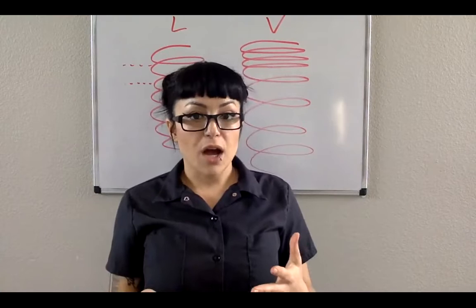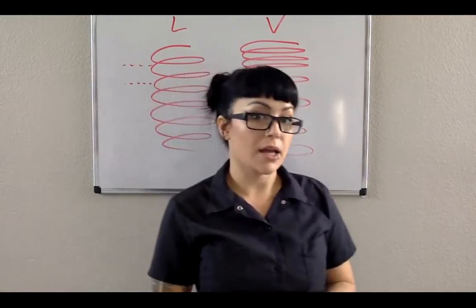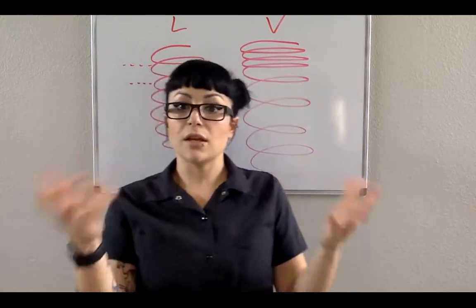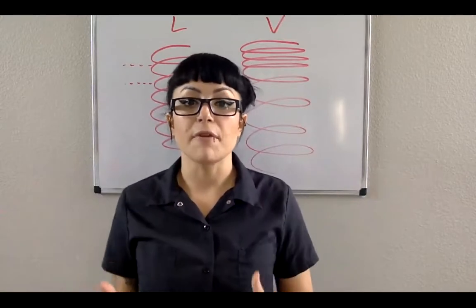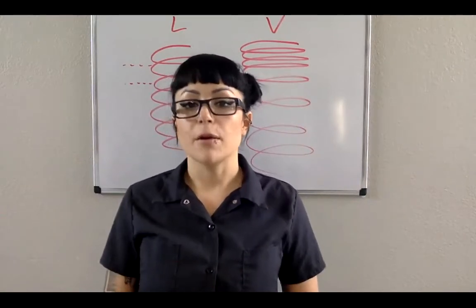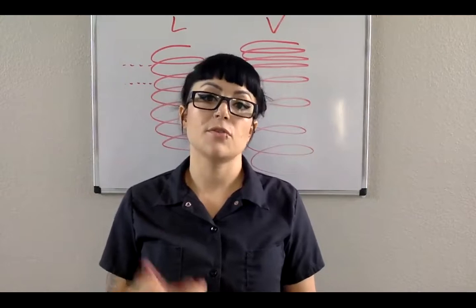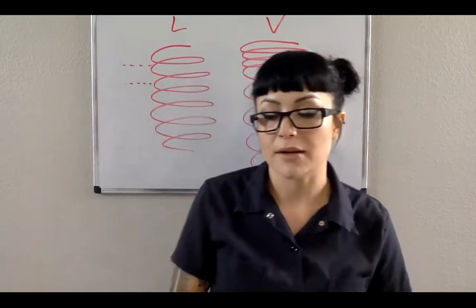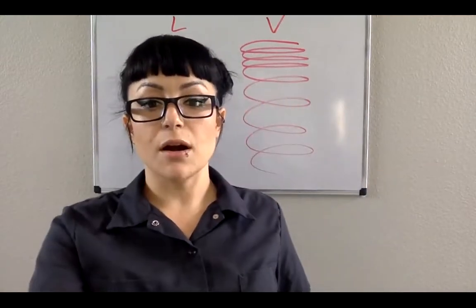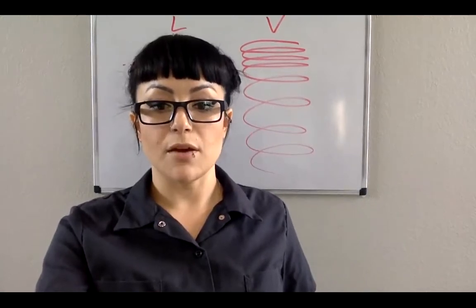Also, what if I have a truck and I work in a business where I need to be loading very heavy things in there? Variable rate springs can help out a ton too, if I've got weight or not in the back. So variable rate springs are very useful in a few applications.